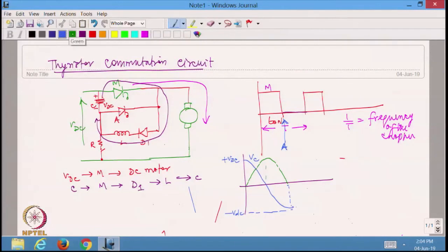So this is going to be the capacitance current waveform, or is this the same as the diode current waveform. So this oscillation time will be equal to pi root LC. All of you know this definitely, right? In an LC circuit, pi root LC is going to be the half cycle time. So within pi root LC, this would have reversed its charge. So you would see that now this has become plus and this has become minus.